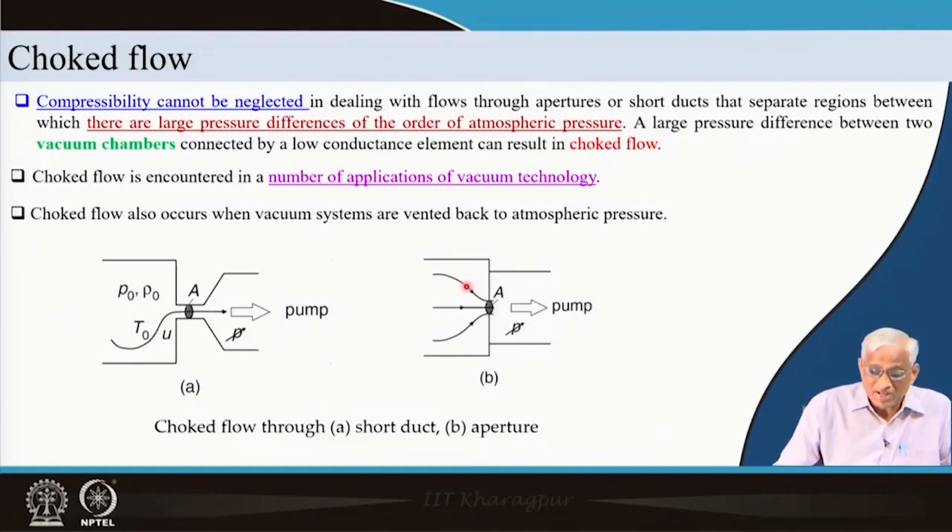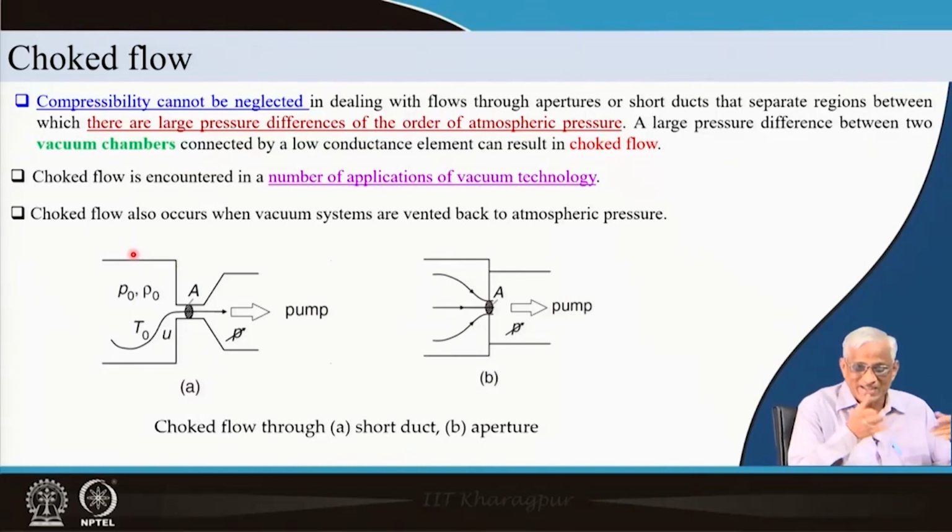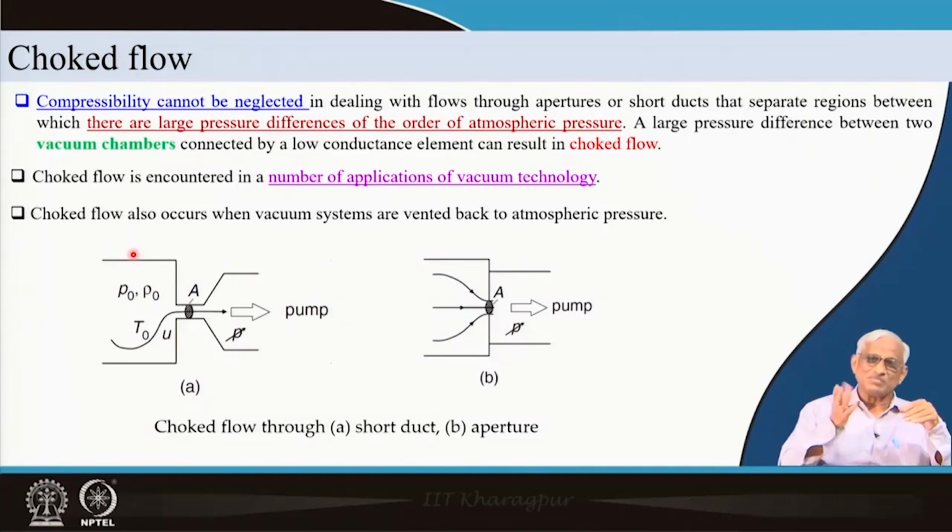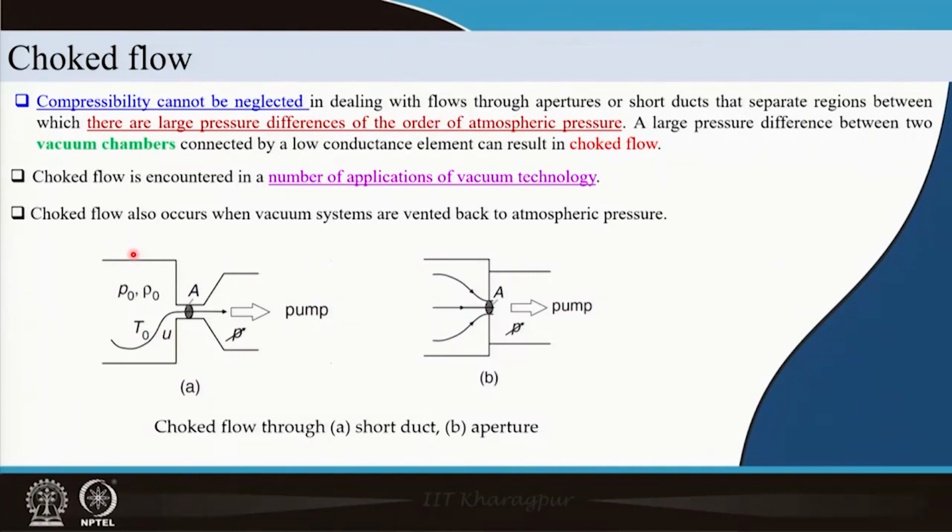Why do we end up here? The pressure drops are huge, unlike normal pressure drops in laminar flow in lecture 32 and lecture 33, etc. There the delta P is maybe 1% of the average P. Here it is not like that, it may be 50%.